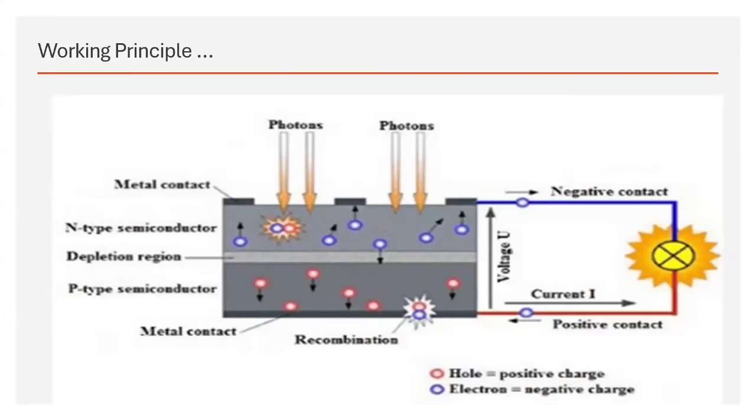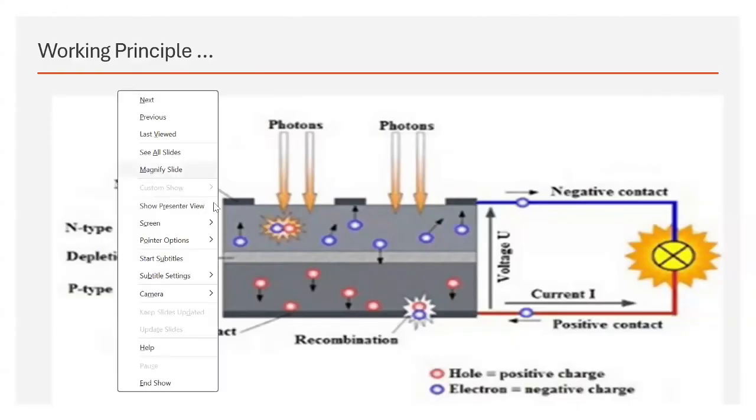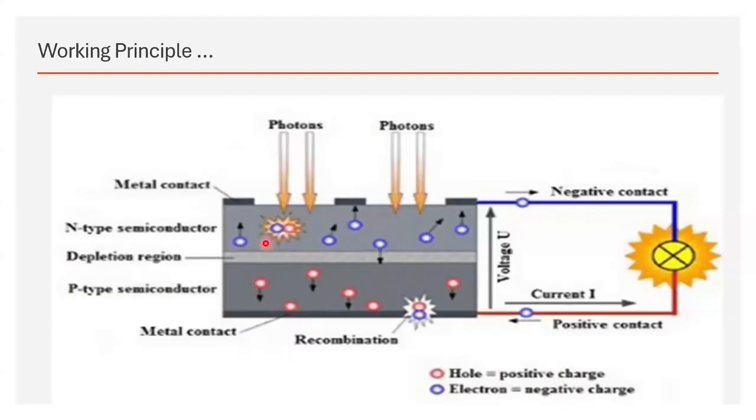So this solar PV cell, or solar photovoltaic cell, is nothing but a PN junction with a depletion region in between them. You can see the upper layer, the outermost layer normally visible to us, is the N-type layer, and the bottom is the P-type layer, and just below that is a metallic substrate or base which forms the positive. There is a nickel plated bracing or aluminum bracing at the top of the cell that you can see normally. These are the negative contact.